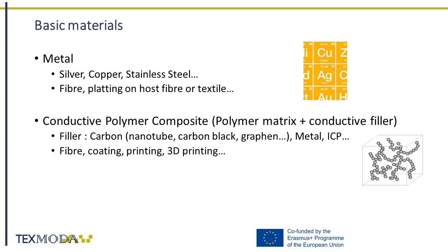Filler could be based on carbon. We could cite carbon nanotube, carbon black, graphene for instance. But metal particles or intrinsic conductive polymer could also be used. CPC are used to make fibers, conductive coating, printing, or 3D printing, for instance.